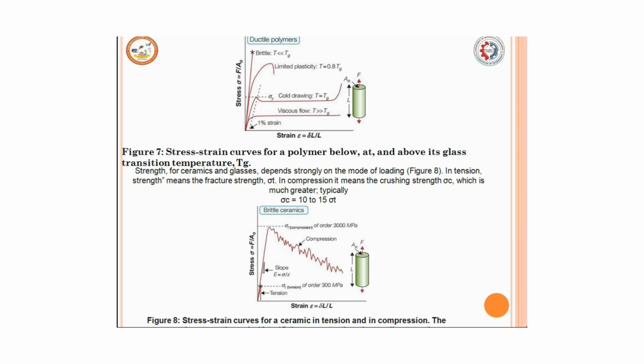When we take ceramic material, in the stress-strain curve it is a brittle material. But you can see that it can take load up to a certain point. After that it will keep on failing further. We cannot expect it to go on. But the compressive strength of the ceramic material is 10 to 15 times greater than the tensile strength. That is the advantage. But it is brittle, meaning if you add load heavily at a certain point, the specimen may break or the material may break.